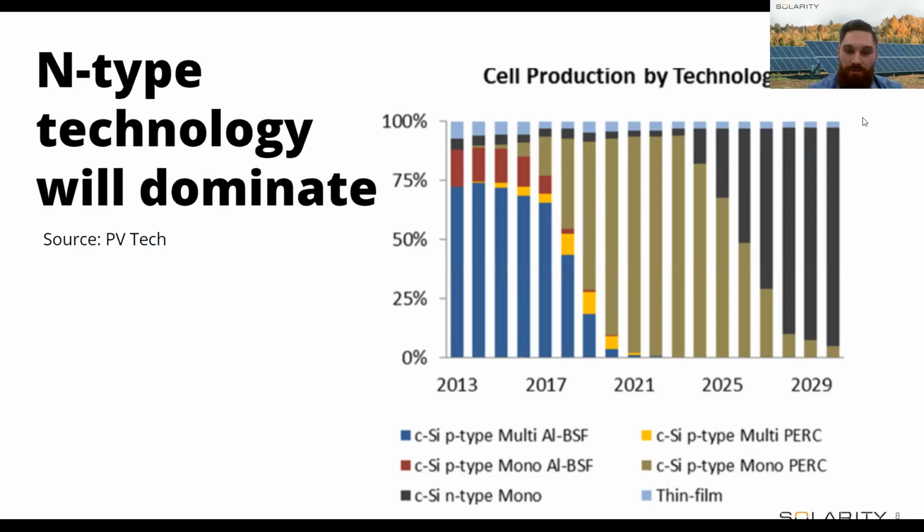In the past, there was a Japan project; Japanese clients are more difficult, or they want high-tech, so it was N-type from the PV manufacturers. Nowadays we can also see a project in Oman with an N-type utility-scale project, and it's a good solution because of the temperature coefficient, for example. So we see from the market that N-type will be more common, not only in residential but also in commercial and utility segments.